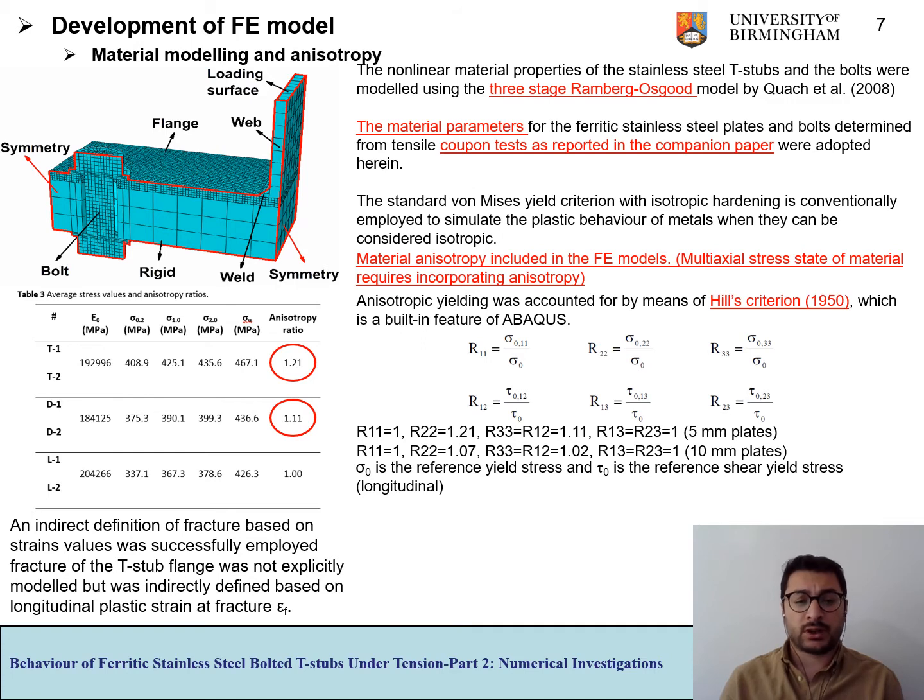For the fracture of the plate, an indirect definition of fracture based on strain values was successfully employed, in which fracture was not explicitly modeled but was indirectly defined based on the longitudinal plastic strain at fracture.